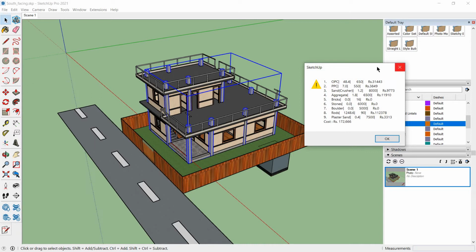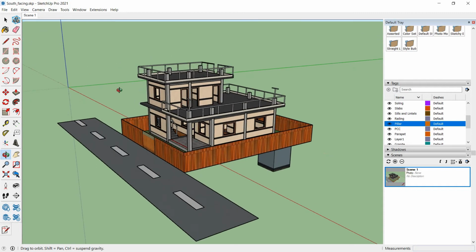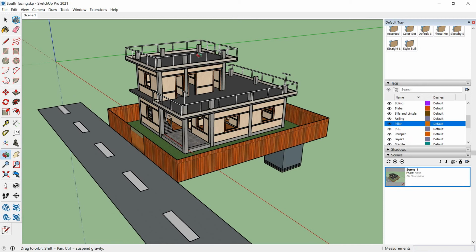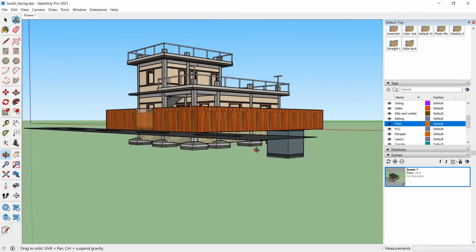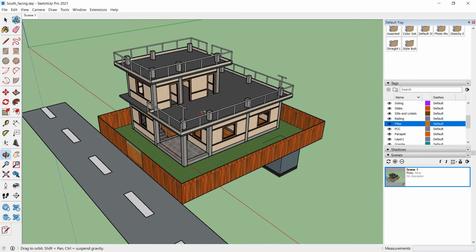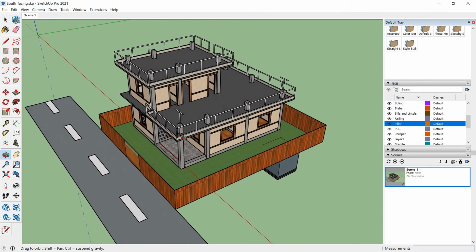This is highly applicable because sometimes the cost of the cement and rods may vary after constructing the 1-story building. So you can easily select the 1st story and then calculate the cost using a different rate, and then for the 2nd story you can select these and calculate the cost for the 2nd story separately and add them. In this way you need not calculate each and every dimension in Excel using a 2D AutoCAD file, but you can easily visualize the calculations on your own.